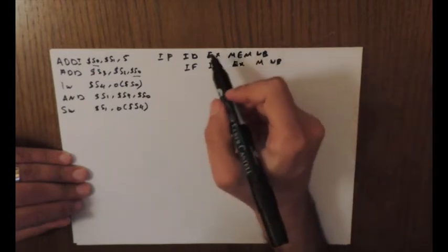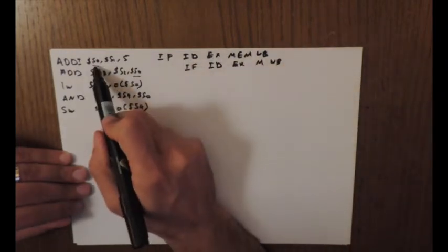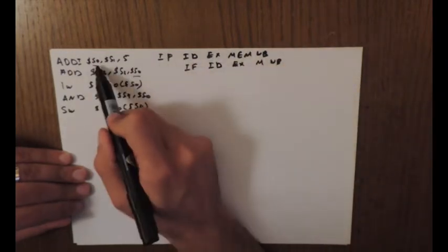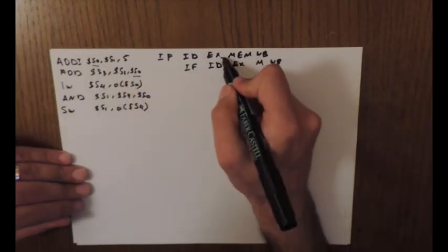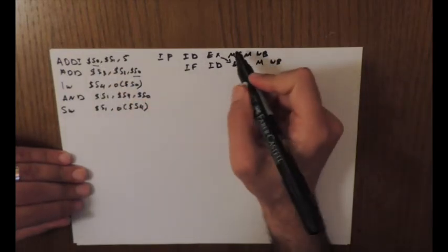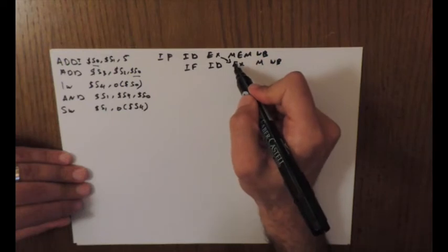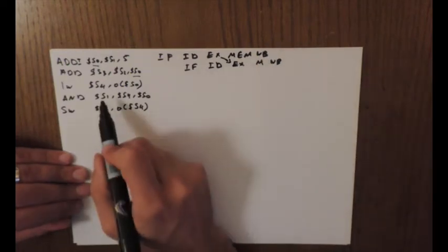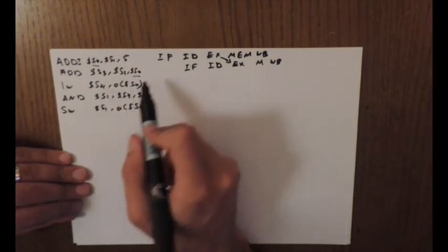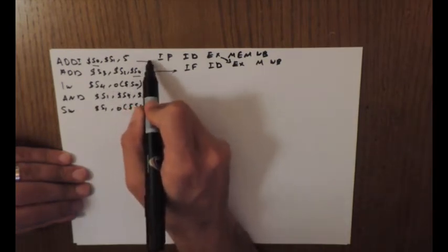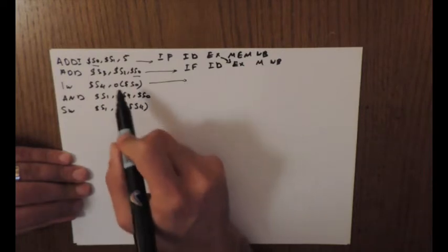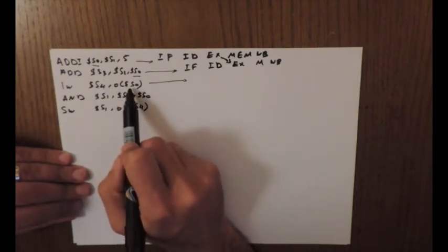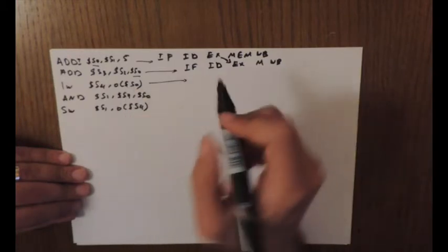So we see here that the value is needed here and is supplied by the execute stage. So now we can add an arrow to indicate that this value is forwarded to the EX stage and no stall is required. Now if you look at the third instruction, the third instruction is a load. It relies on S0. So let's see if we can do a forwarding here.